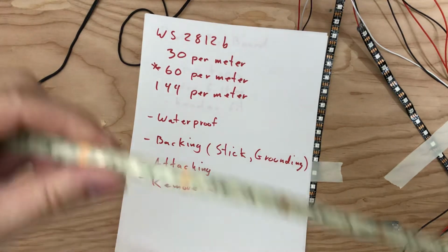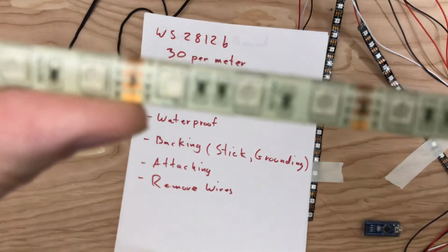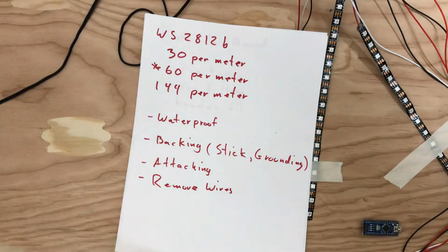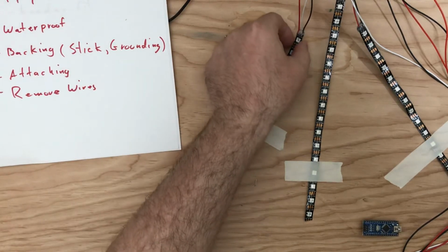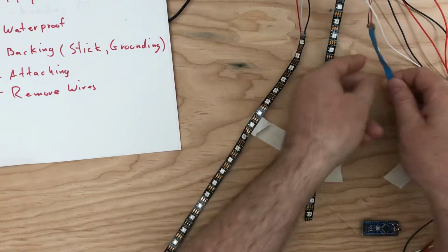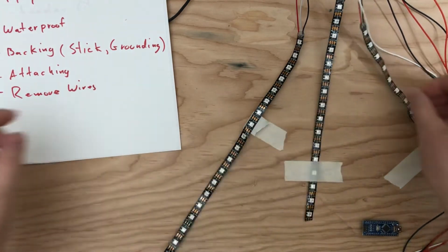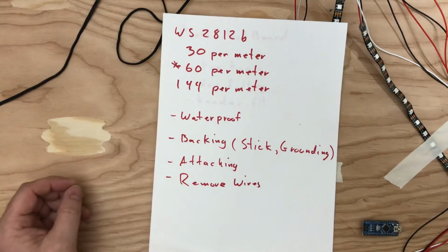I have another strip here. It's not the WS2812s, but a different type of strip, and you can see there's a silicone dome on top of them. These are good too, but it takes up a little bit more space, and that's what you'd have to look for when you're buying them. Some of the backing, you have to look at them. These ones I got from 2 different vendors. This one has no backing on the back. This one, if you can see it on the camera, has a blue peel-off sticky side. So depending what you get, just be prepared for that.